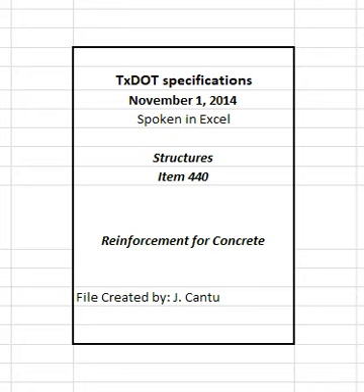Locate the reinforcement accurately in the forms, and hold it firmly in place before and during concrete placement by means of bar supports that are adequate in strength and number to prevent displacement and keep the reinforcement at the proper distance from the forms. Provide bar supports in accordance with the CRSI Manual of Standard Practice.